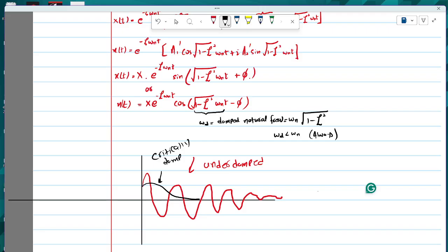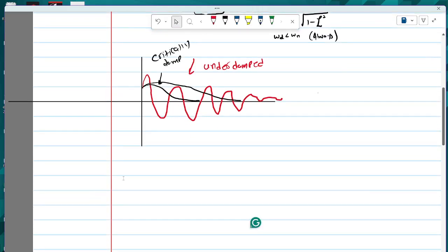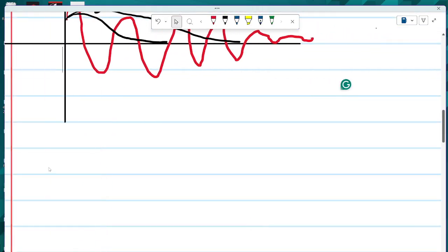And then there's the overdamped system, which lets the system move with a large amplitude and then slowly reach the rest position. It also ensures that there is no vibration, but it takes more time compared to the critically damped system. Now, looking at case 2, I just explained all of these cases. Case 1 was underdamped, case 2 is critically damped.